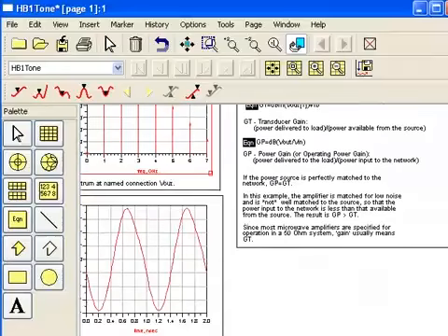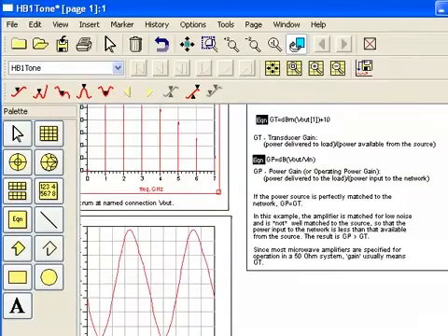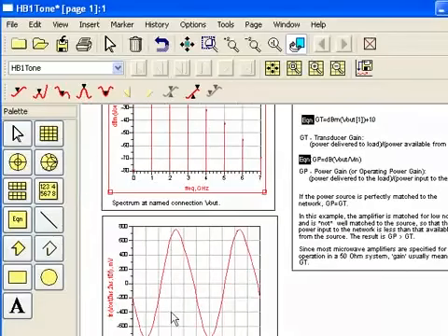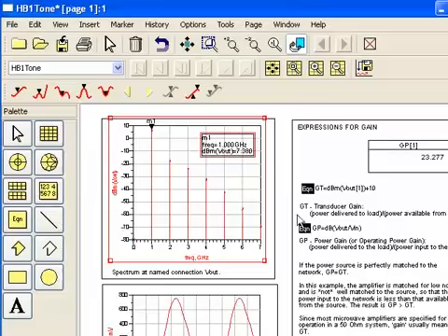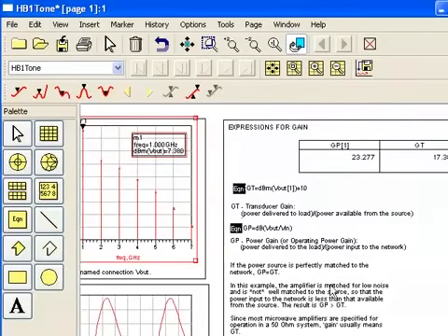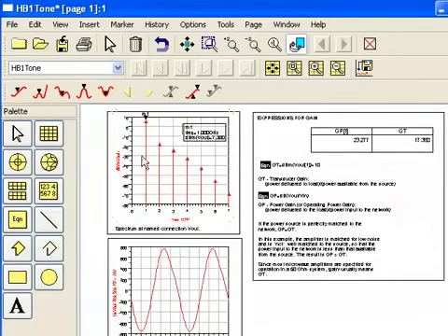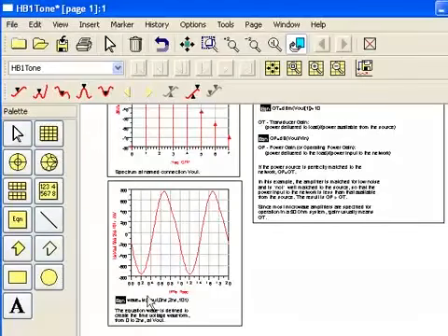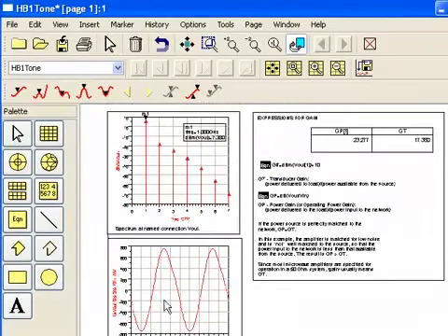And for the waveform, you can always take harmonic balance data and use a transform that you see here, and then it gives you the waveform. Finally, there are 2 equations here for transducer gain and power gain, and again, using V in and V out, you can make calculations. So this is the basic harmonic balance results, the spectrum with the amplitude, the time domain waveform using the TS function on V out, and also equations that give you power.